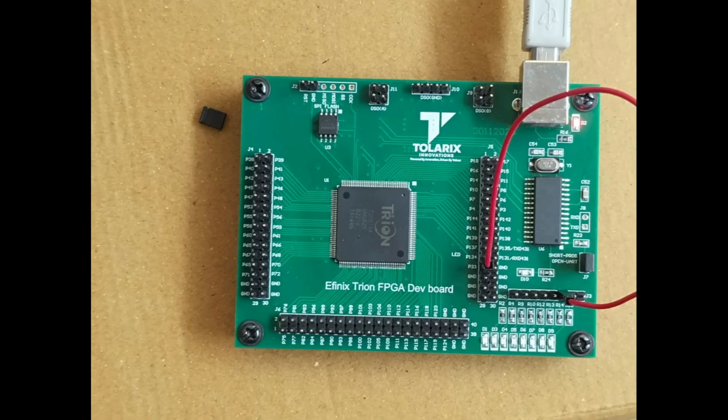In this setup, FPGA pin number 18 is used as the input, and FPGA pin number 33 is used as the output connected to an LED. First, leave pin 18 open. Since a weak pull-up is enabled, this applies a logic 1 at the input. Because this is a NOT gate, the output becomes logic 0, and the LED remains off.